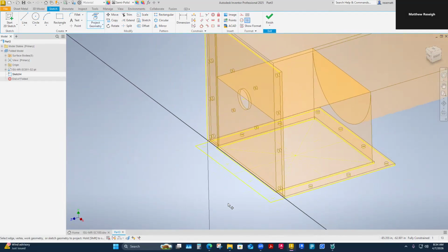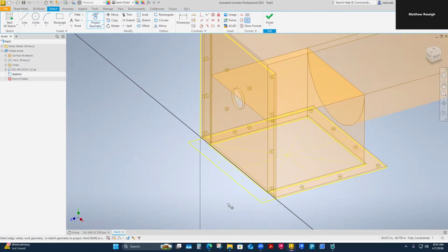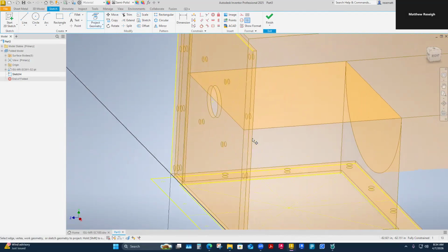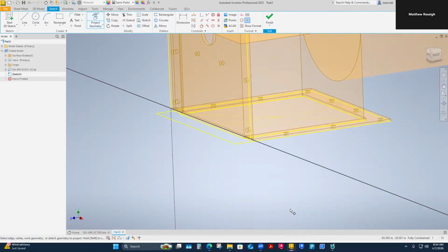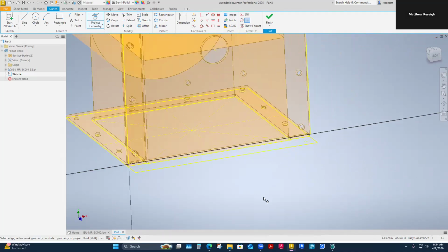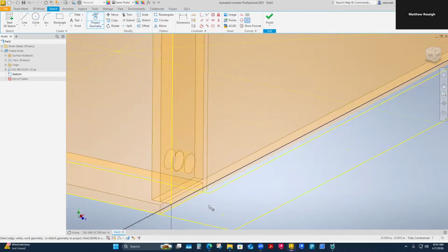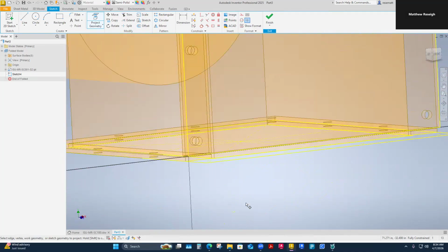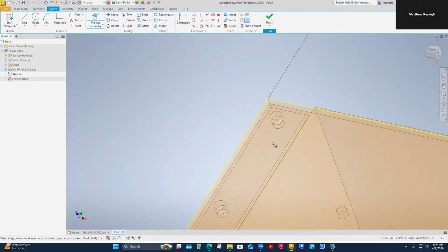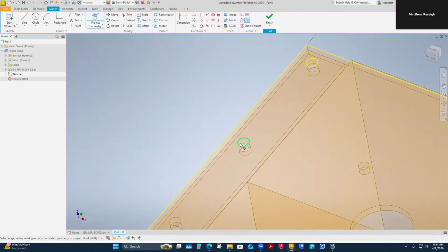It'll act like a sketch does in a part, and when I use it for something, I think it will turn itself off, like sketches do once they've been consumed or used for a feature. I think it does that here too. So these were not new sketches. They came in with the part. And then all I've got to do is trace this thing, get all the clearance holes for the bolts.